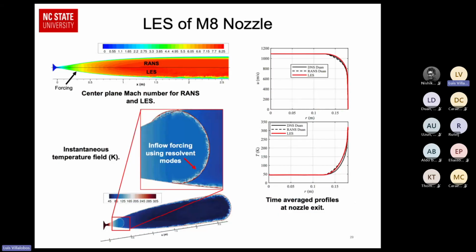Yeah, I'm not really sure how you would implement a recycling rescaling in this sort of case, for a bump, like what's up and down. Yeah, Ali did something like that. So you can do recycle rescaling, but it's not perfect. If you have an estimate of what the boundary layer thickness is and what the skin friction and response conditions are, you can map those things. I actually think there was a cone DNS or LES paper recently that did a volumetric rescaling method, so there might be ways now to do that.